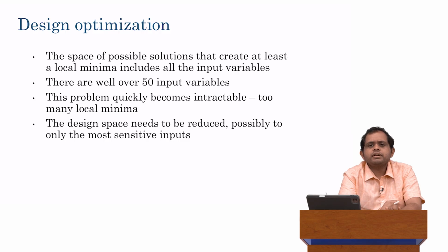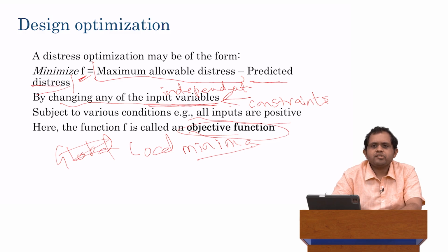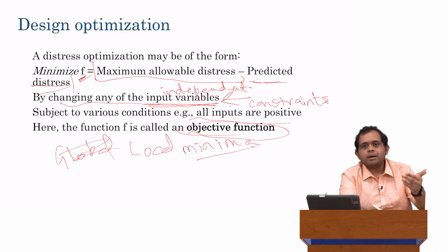And as you can probably relate to it, how is this related to JPCP design? You'll probably see that it is fairly close. What are we doing in JPCP design? What are our independent variables? Thickness, material properties, type of materials, etc. So those are our independent variables. Our predicted distress is what we've been talking about so far. That's what comes out of a mechanistic empirical design.